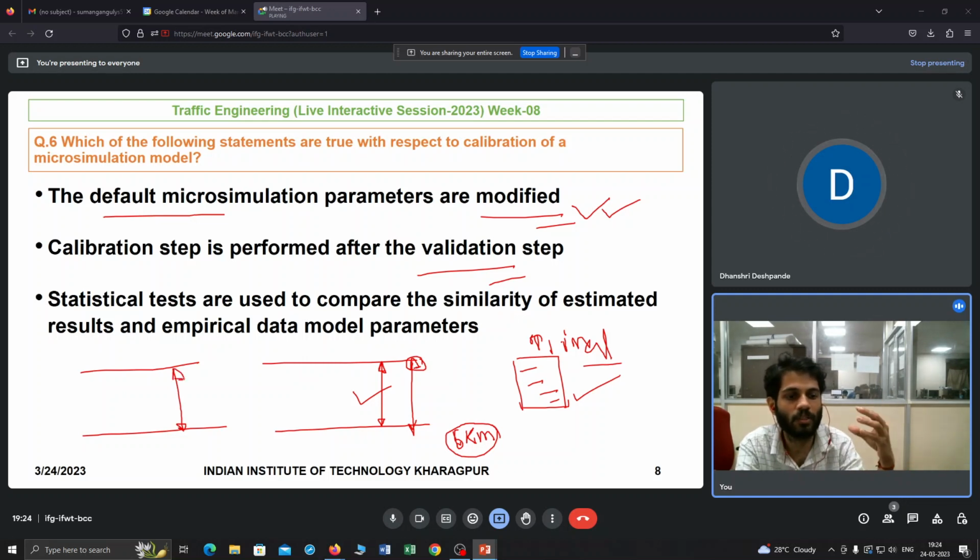That same parameters I will use for my different models. So in this case, due to variability in your traffic as well as your road geometry conditions, number of lanes, the width of the lanes, and the parking and encroachment, those scenarios are different. So is it that your same parameters are valid for this also? It may not be so, right? So in that case also you need a validation.